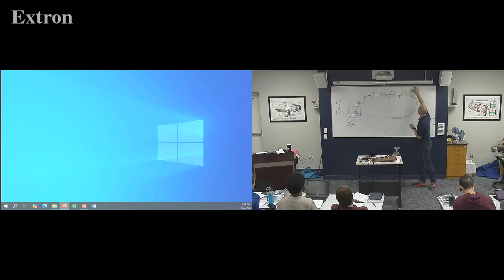So a voltmeter, and it's open in the wire. What would that read? We're going to read 12 volts, because my potential difference between my plus and my minus is 12. My minus is going to stay the same all the way up here. So this point is the exact same as this point.